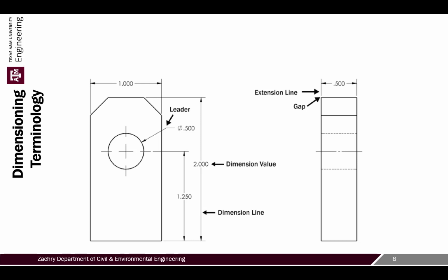So when we're normally talking about curves and all that, we're going to identify the curve using a leader. And so the leader is going to point towards the feature that you're identifying, but it's not going to bracket it. So in this case, it's giving me my dimension for the leader. If you look at the overall width, you have it going from my left to right. It is showing what it's dimensioning. It's dimensioning the overall width, and it's giving me that information.